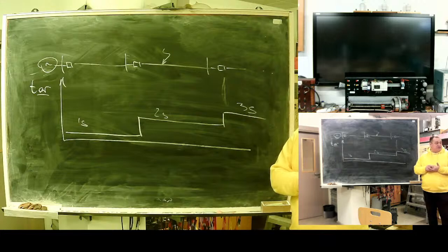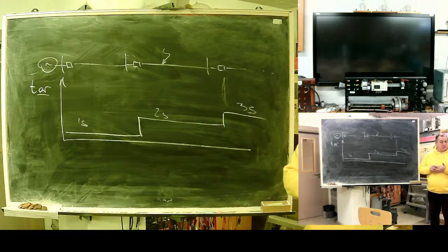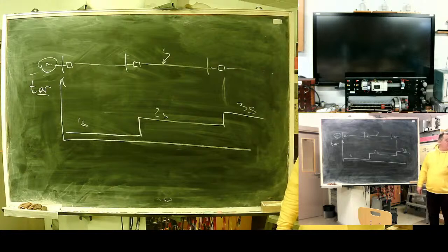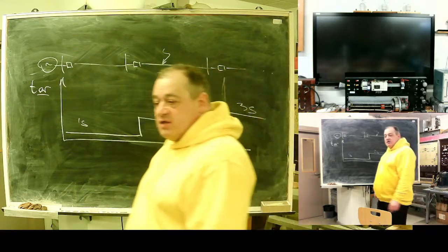Otherwise, we have a persistent fault: disconnection, reclosing, the fault does not disappear. What happens? Okay, protection acts, the switch disconnects. Can we allow reclosing? No. Okay, two times may be allowed, but not more, because if more, our switch will blow. We will switch on into the fault multiple times.